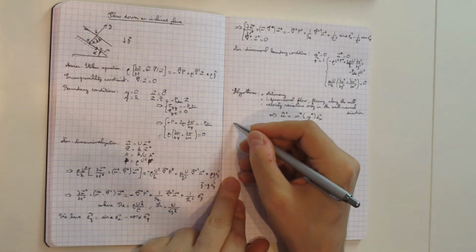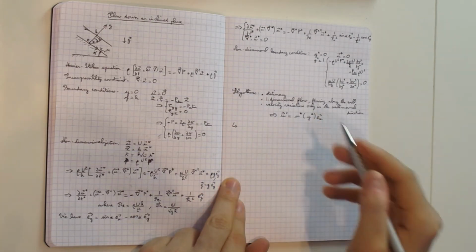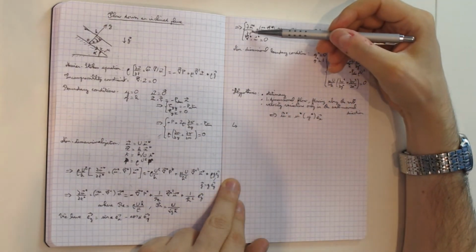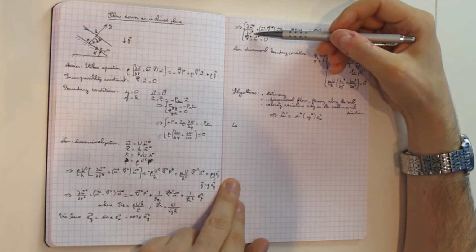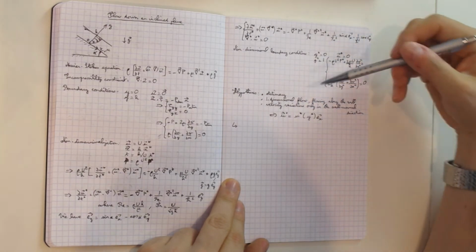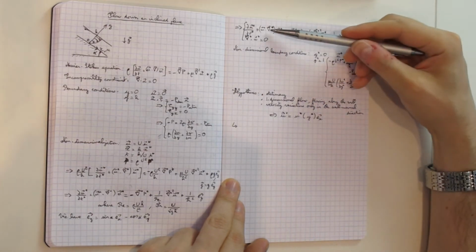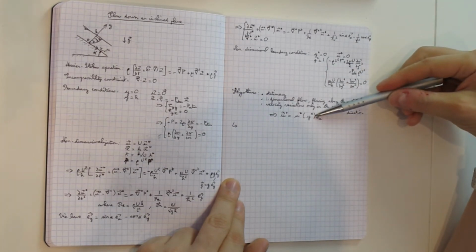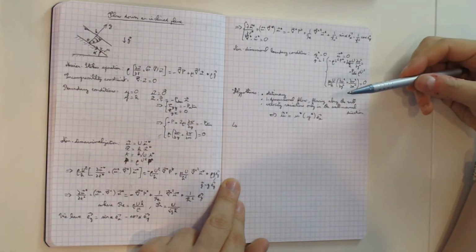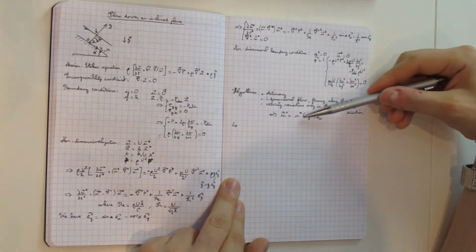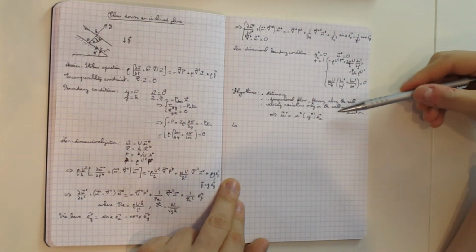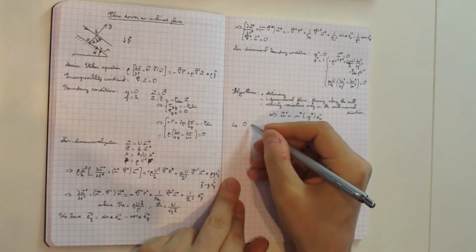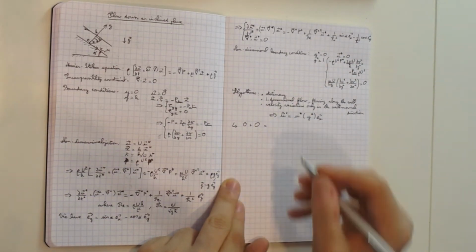So the Navier-Stokes equation becomes, for the component u in the x direction, du by dt, which is 0, because u does not depend on t, plus u dot grad u, so that's going to be u du by dx, but u does not depend on x, so that's 0, plus v du by dy, well, but v equals 0, there's no component of velocity in the y direction, so that term is also 0, so the left-hand side is going to give us zeros.